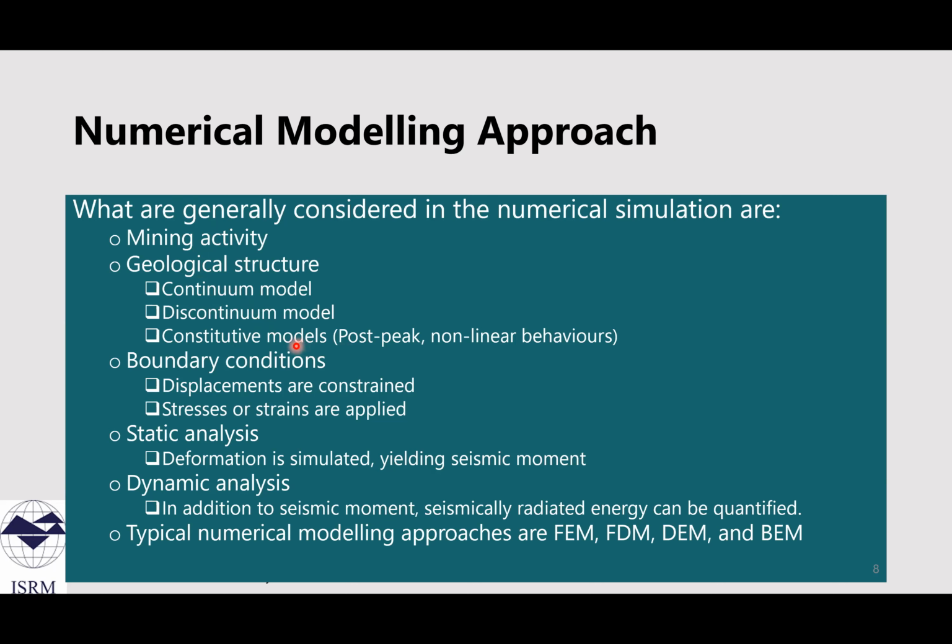These negative quantities correspond to the source state below the failure criterion. So this indicates there is no risk for fault slip. This result is not consistent with the seismic monitoring result, showing the intense seismic activity.